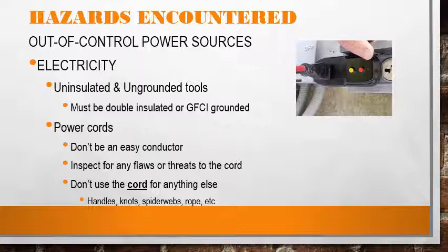Don't drape power cords around the job site like spider webs from one place to another. Use the nearest outlet. Don't use your power cords as rope to lift things or to lower things. General rule of thumb is use your power cord only for a power cord.